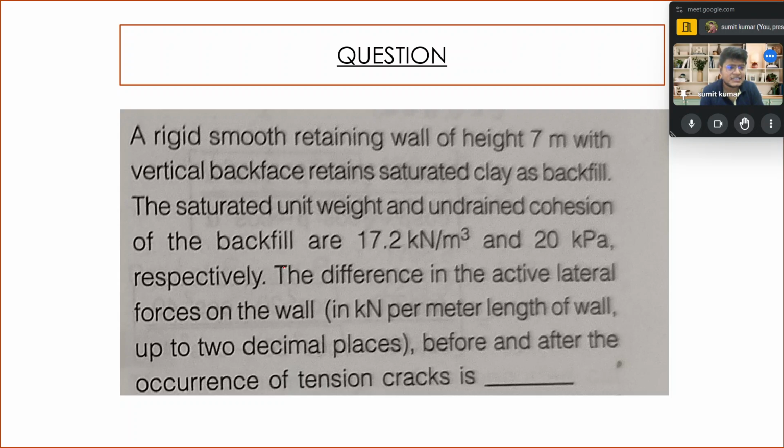Specifically in any examination, if they are asking the earth pressure at a specific section in kilonewton per meter square, and we calculate the total earth pressure, that is the area. Sometimes they ask for the resultant earth pressure acting, which we could also calculate for the simple section as 1 by 2 into k gamma h square, acting at h by 3 from the base.